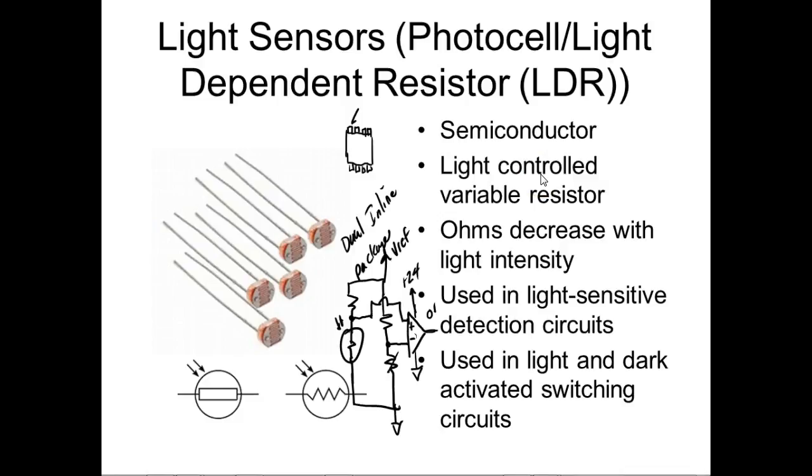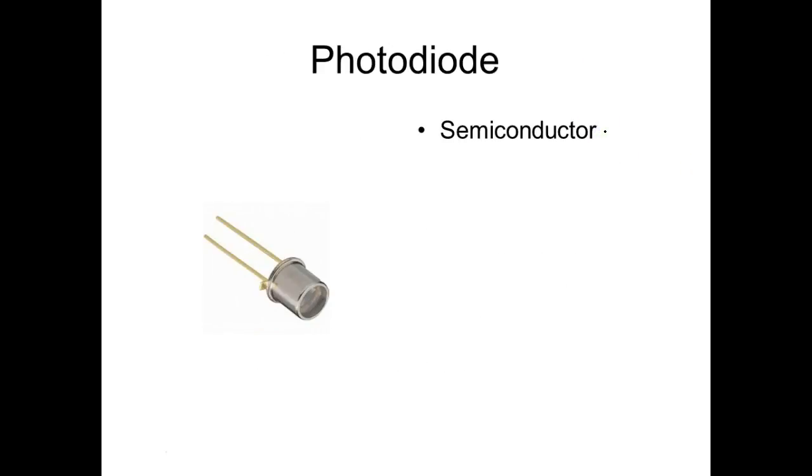Did it come back up there, guys? So a photodiode, this would be the actual symbol. So we come over here. This is a symbol for a diode. And then what we would do is we'd come over here, and it might be in a circle. I'm not going to put it on there. And it would come in and have what? Instead of the arrows pointing out, they're pointing in. And this is a symbol for a photodiode.